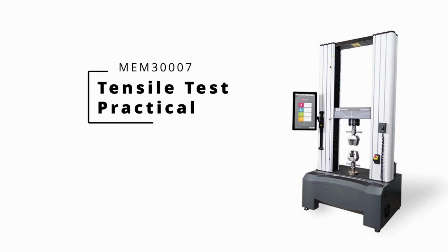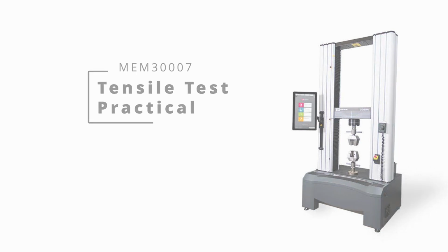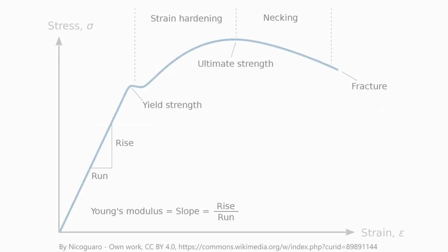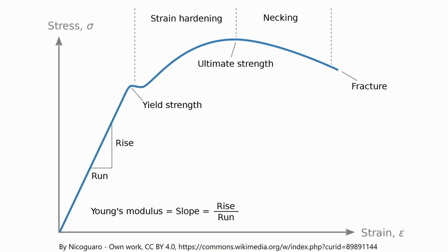The tensile tester will slowly separate the tensile clamps at a constant speed, applying an ever-increasing load, and will plot this against the change in length of the sample. The graph produced by the universal testing machine is typically known as a stress-strain curve.